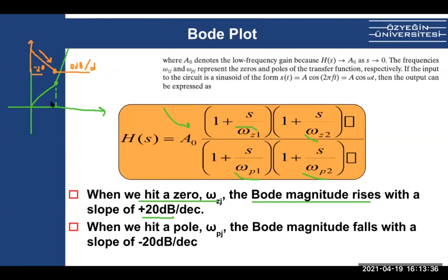If you want to notice a pole, well, this one, is it a pole or zero? Question goes to Taha. I think it's not zero, it's a pole. It's a pole, right? Because now the magnitude slope is minus 20 dB. It was increasing 20 dB. Now the increase is not there anymore. We don't see any increase, 0 dB.